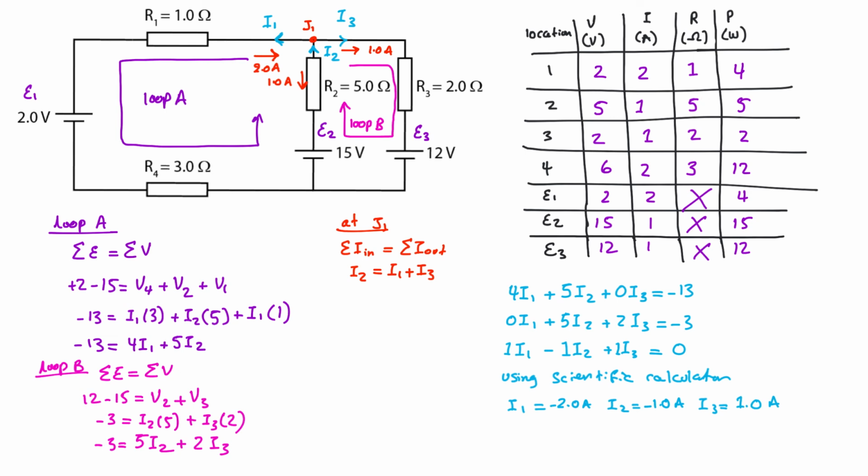And then the rest of it is much easier, because you can always calculate voltage, or potential difference, by current multiplied by resistance. And sometimes we write potential difference like this as well. It all depends. I'm using the IB format here where we don't include the delta, but in most cases, including delta is the proper way. And we find power by the equation I times V. We can also use other equations for it, but once we have these two, it's just easy to multiply them out.